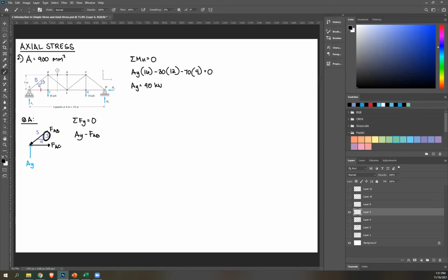So I gotta get the vertical component. So copy the side that's also vertical. So that's 3 over hypotenuse 5. Okay, there's no other force that has a vertical component, so equate to 0. Considering AY is 40, please solve what's FAB.